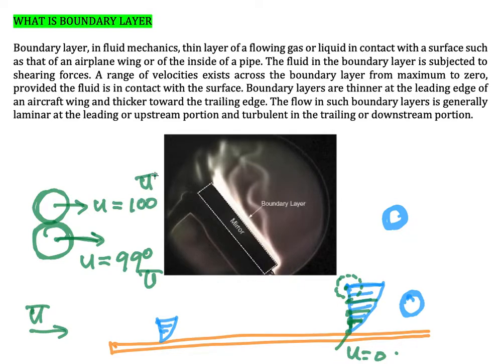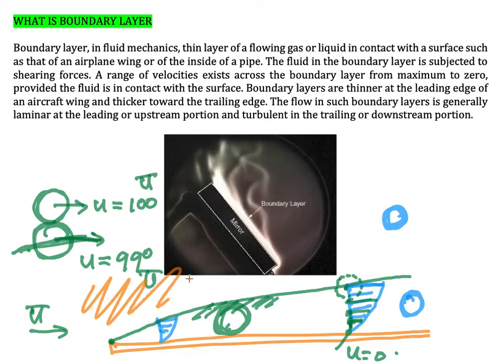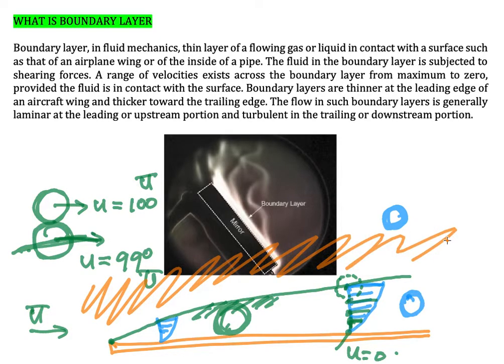Now we could draw a borderline on this molecule, meaning we just connect here to this one and to this one. In this region, the velocity changes according to the velocity profile. But in this region, the velocity doesn't have any velocity profile. All the velocity will have the value of capital U, because for the molecules in this region, u is equal to 100% of U.